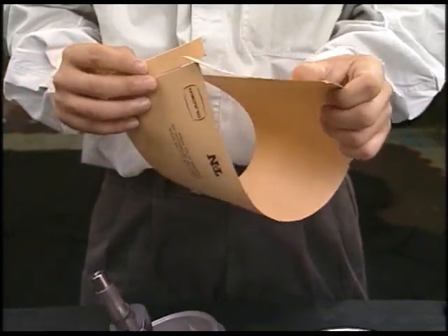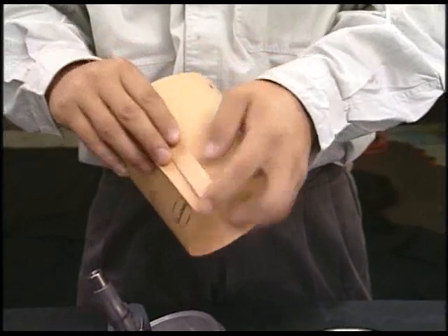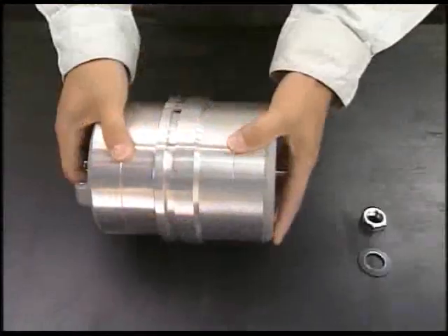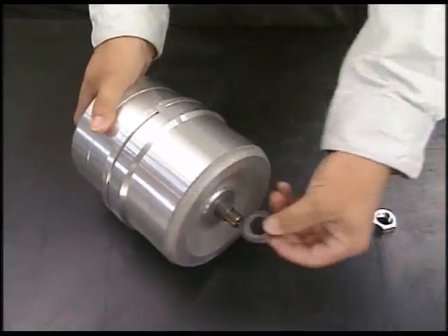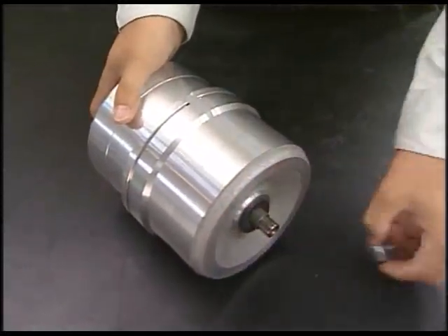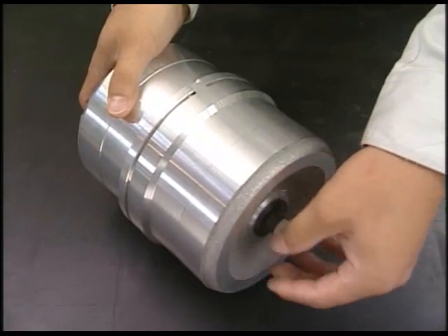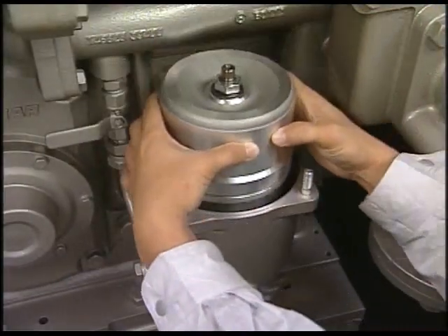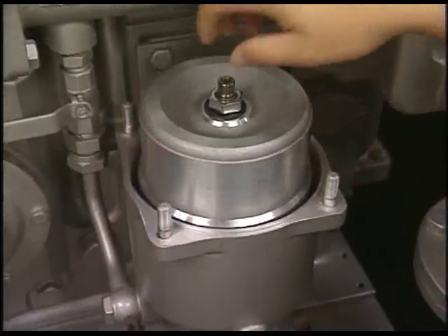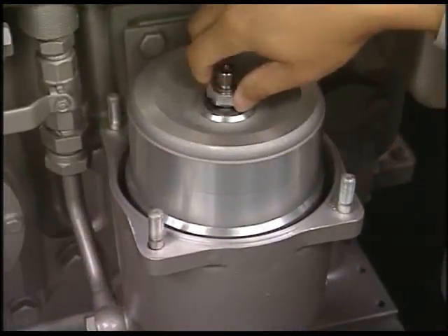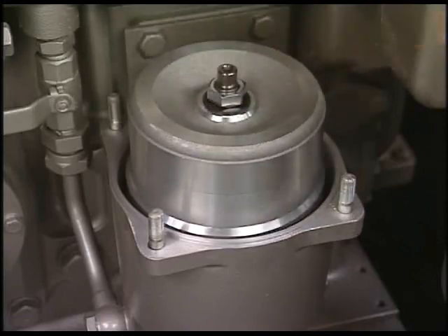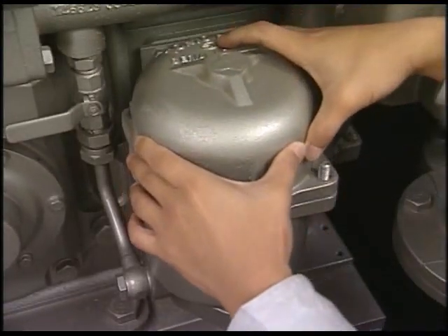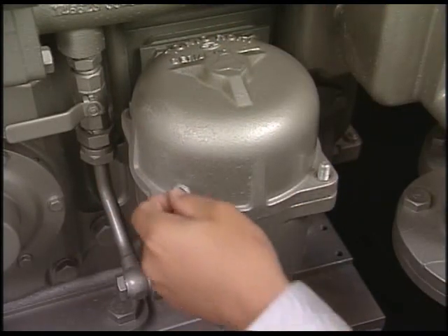After renewing the O-ring, reassemble the centrifugal bypass strainer in reverse procedure for disassembly. If the paper insert is put in, it will be easy to remove the sludge next time. Fix the reassembled rotor assembly on the main body and check that it smoothly rotates. Fix the main body cover, tighten the nut, and the work will be completed.